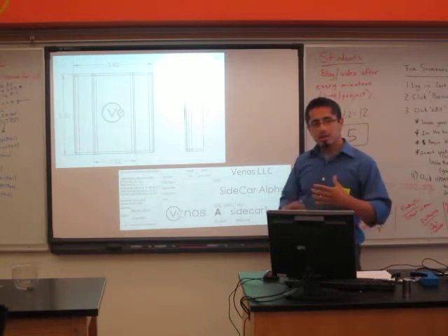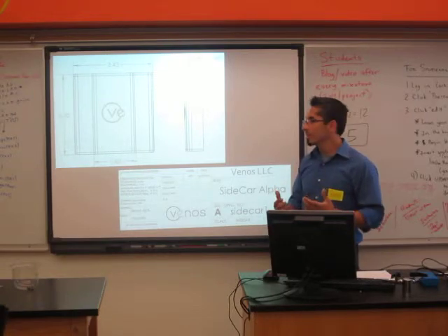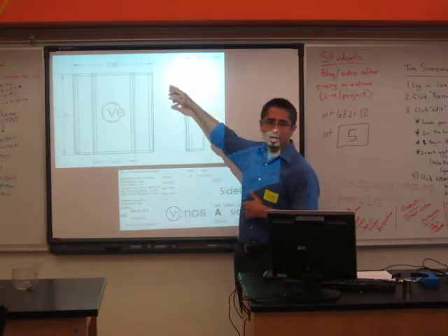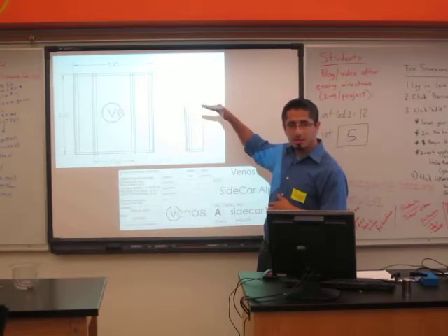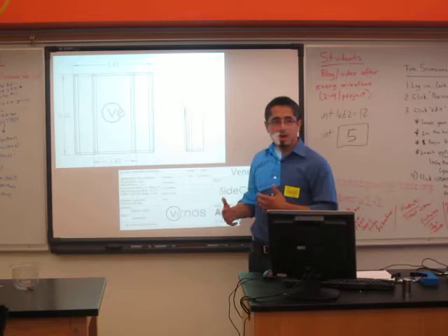In CAD and engineering, it's a little different the way you term out your significant digits. You don't just say, all right, I'm going to put 5 decimal places, and that means I only have that last decimal. It can only go plus or minus a little bit. You actually say what your dimension tolerances are.